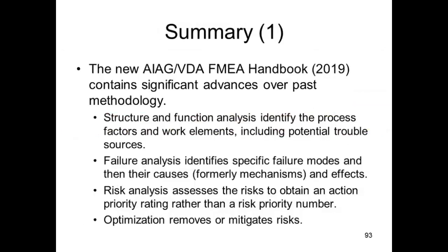Okay, summary. The AIAG VDA FMEA handbook, it just came out last year, less than a year ago, I think, contains significant advances over past methodology. Structure and function analysis identify the process factors and work elements, including potential trouble sources. Failure analysis identifies the failure modes and their causes. Remember, the failure cause was formerly the failure mechanism. Failure cause and failure mechanism play the same role in FMEA.